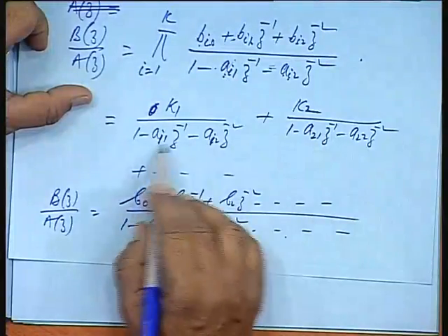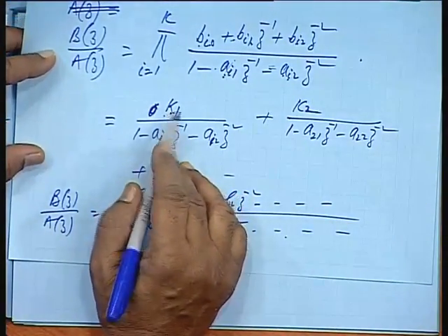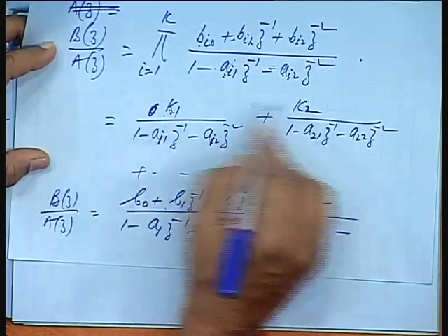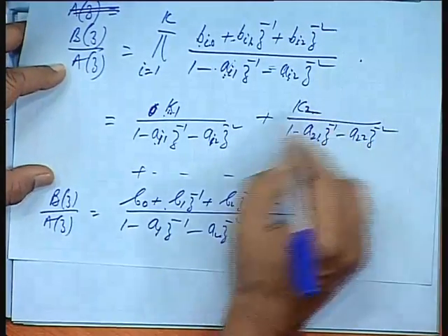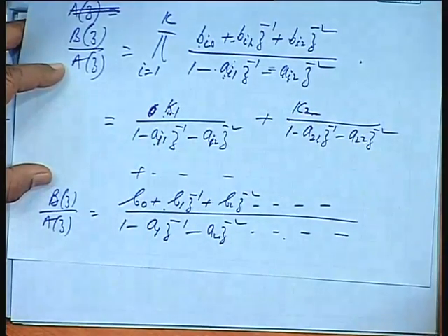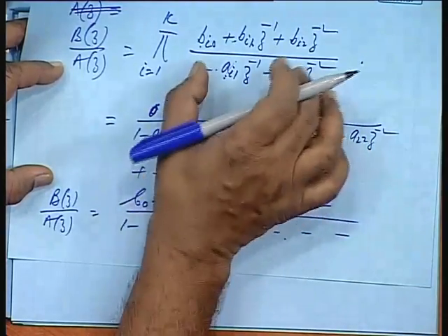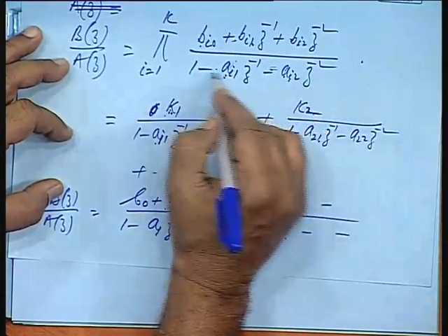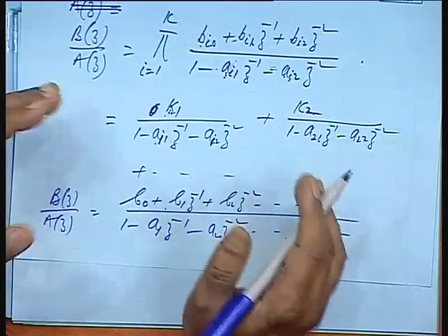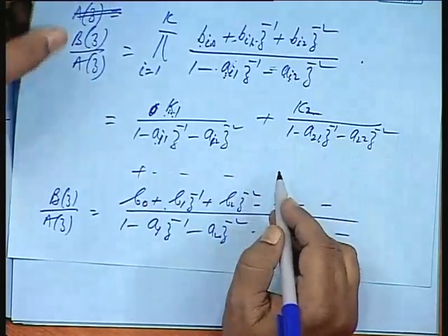However, in this case the poles are restricted, zeros are not known, they are in a very complex mode, because if you add up k1 into a21, a22, k2 into a11, a12 and so on, all these terms will appear. So, here only the poles will be affected by the variation of these parameters, but these parameters will not be affecting the zeros independently.